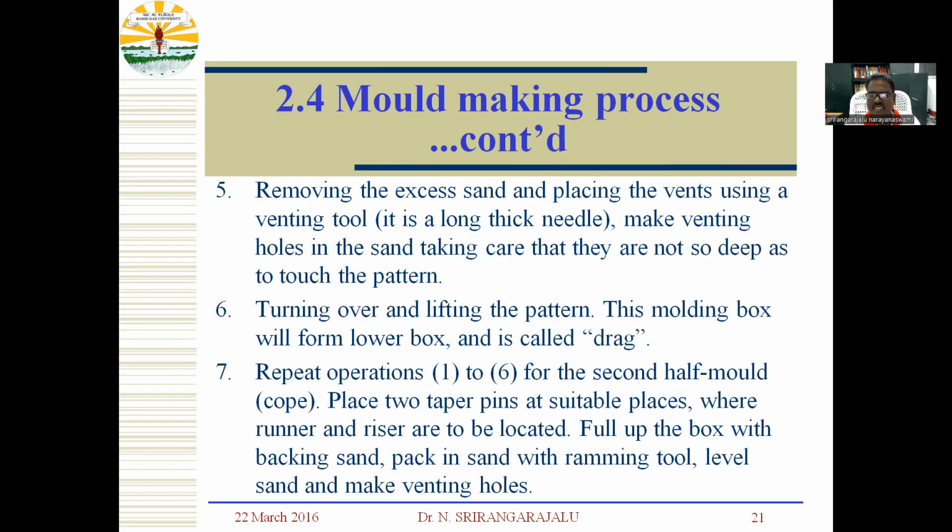Removing the excess sand and placing the vents using a venting tool. It is a long, thick needle. Make venting holes in the sand, taking care that they are not so deep as to touch the pattern. Turn over and lift the pattern. This molding box will form the lower box and is called the drag. Repeat operations 1 to 6 for the second half of the mold, the cope.